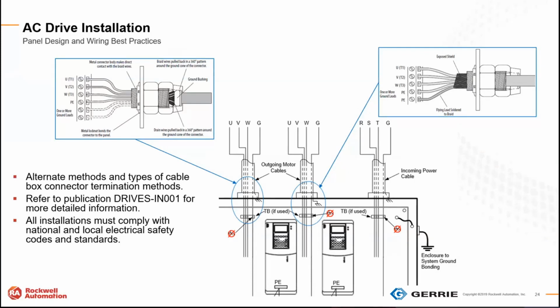And this one as well is the incoming actual box connectors. What are we using for that as well? The big thing here is when we see a lot of the Tech cable come in, just don't rely on the Tech jacket as the only ground conductor when we're using it for VFD installations. That's the big one there.